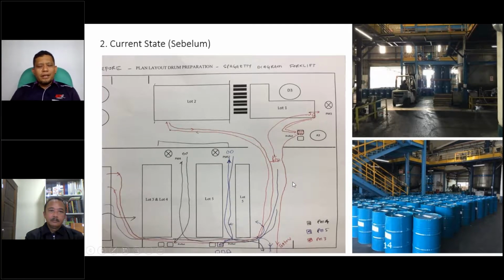So I said I don't want forklifts in this area. It's dangerous. You have the dilution tank, and you have the reactor. Actually, they have two reactors in here. There's a lot of movement, and people also walk here to take samples. So I told the plant manager that if necessary, we want to remove all these drumming and packing activities to outside. If necessary, all will be done around here, outside.